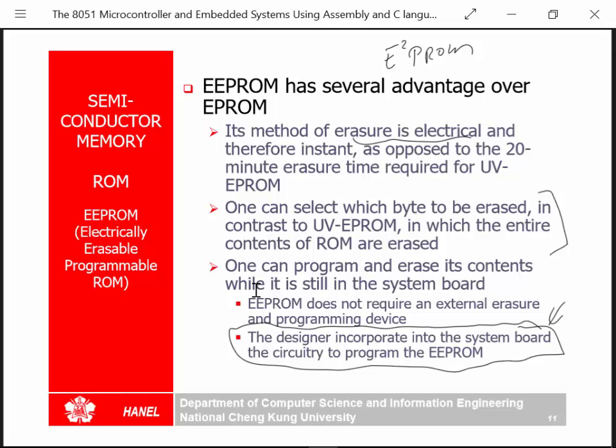This is extremely important because if you look at our chip, it's a surface mount chip. It's not a socketed chip. Most of the Silicon Labs chips are not socketed. Matter of fact, most microcontrollers today are not socketed. They're surface mount, and being surface mount means that unsoldering and resoldering is not a trivial matter. There are some sockets for them.